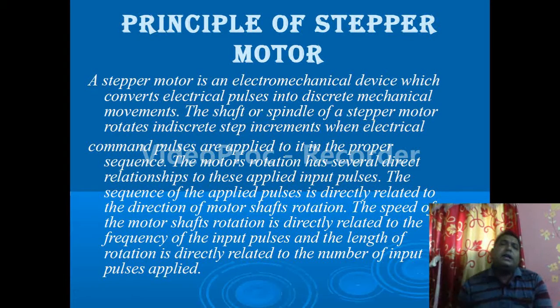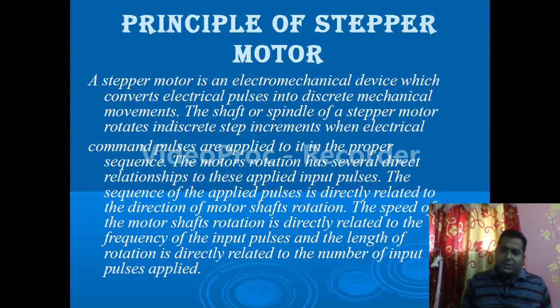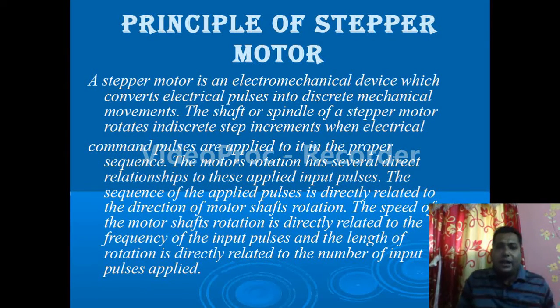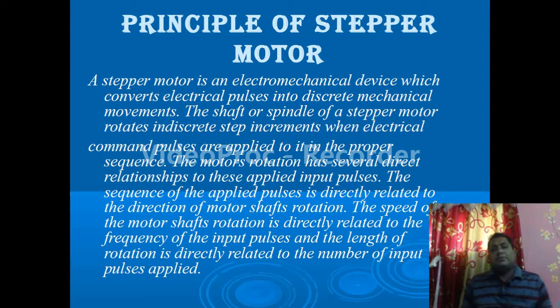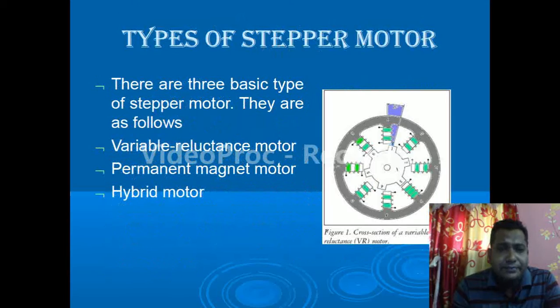So two things we can say over here: how fast the machine is acting depends upon the frequency of the system, and how far it will rotate, or how many steps it will rotate, depends upon the number of pulses, the number of inputs we are giving to the system. So now coming to the next slide.